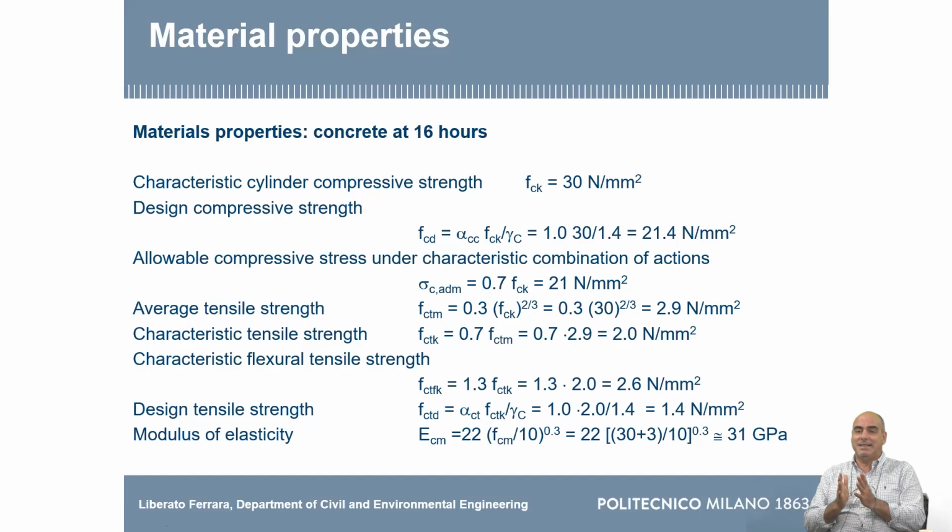So this moment, these 16 hours, they last for just a very limited moment in which you release the pre-stressing and move it. Over time, it will increase. So you can accept some higher stresses in this stage.